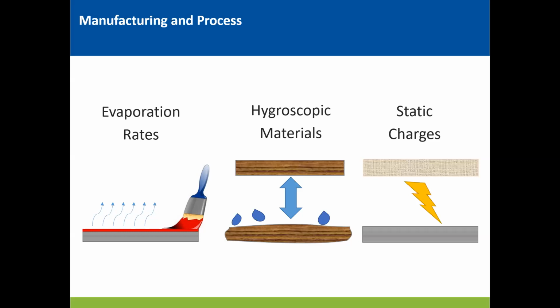Conversely, if you're trying to apply paint in a condition like we showed earlier with the 4% relative humidity inside the home, what you might find is that the paint dries too quickly on the surface, and then you get some cracking or deterioration of the paint as it dries. So a lot of those processes will be looking for a specific balance depending on what product is being applied. And certainly if you look at the back of paint cans and other coatings, you'll see that there are specifications for temperature and humidity at which the product is best applied.